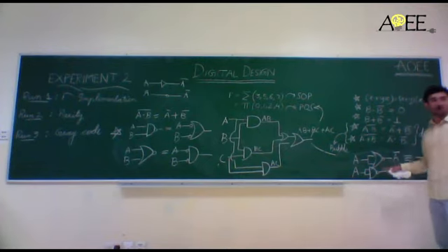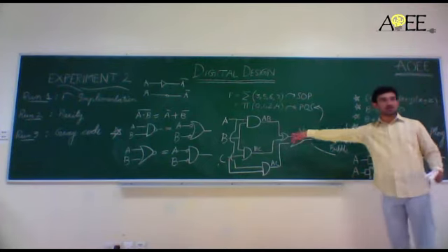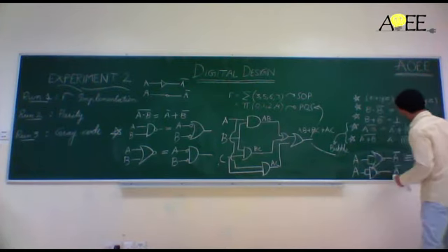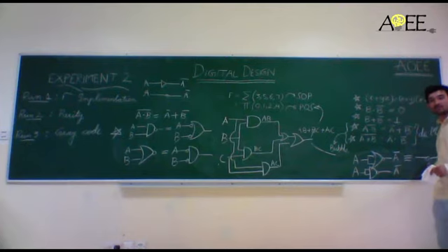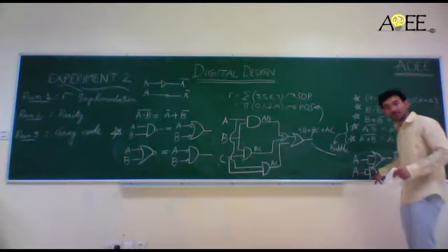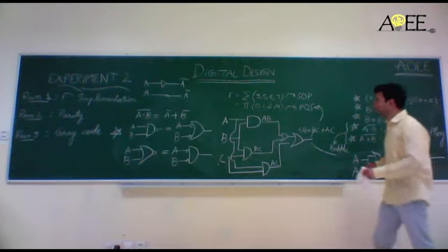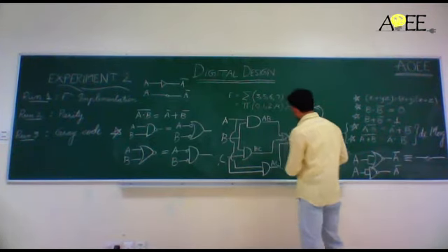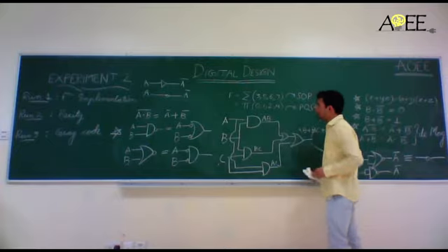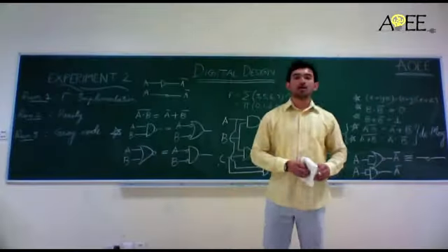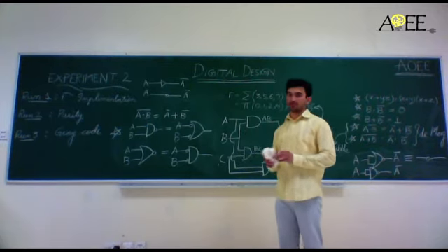This has importance because when we implement using NAND and OR gates, we will realize that in some places we are left with just bubbles, and wherever we are left with bubbles, we can replace them with NOR gates and NAND gates. Okay, so how does bubble pushing work? Fine, we have A bar and B bar. Alright, now we start with what is bubble pushing.